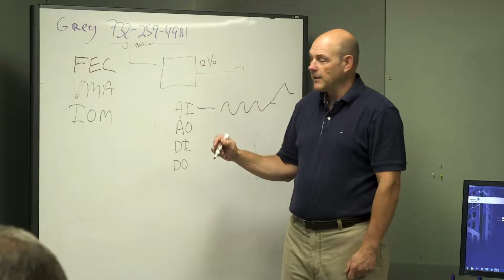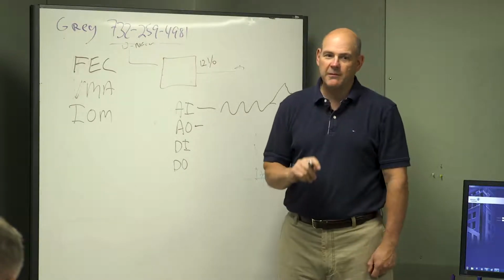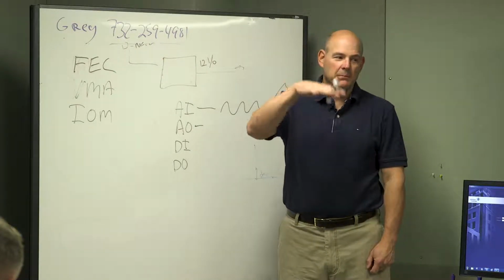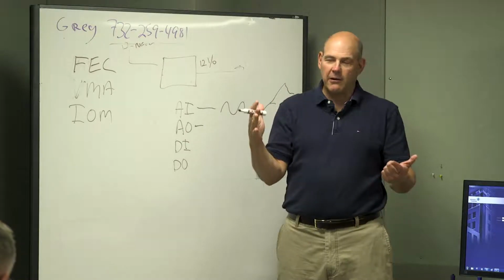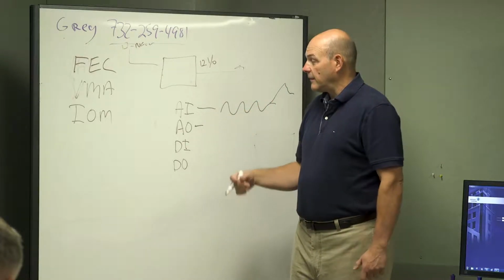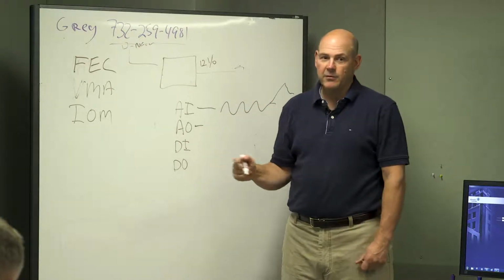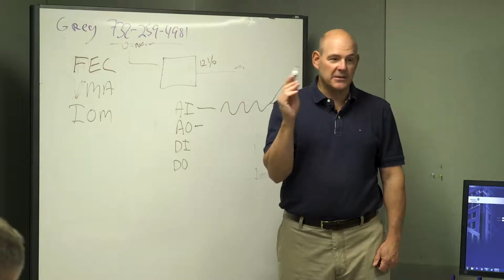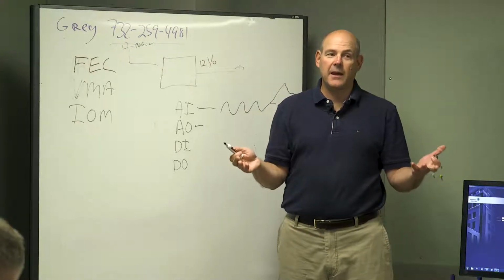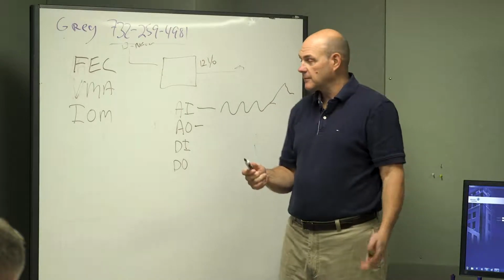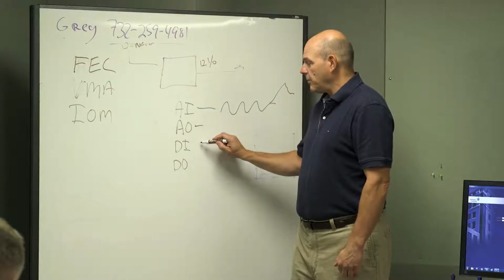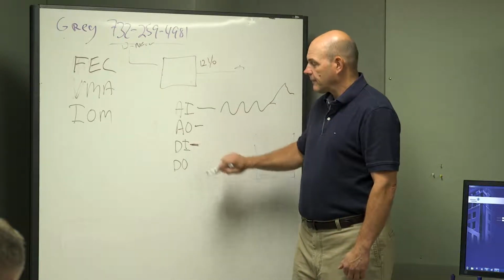And it's an input. Same thing with the output. That would be a valve that's going to keep modulating for an air handler to maintain temperature. In this case, it could be an output to a tower fan that says to speed up to maintain tower temperature. All right? A digital input is on-off.